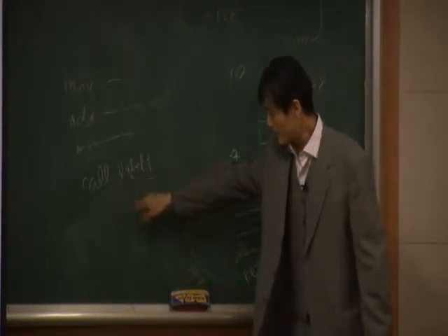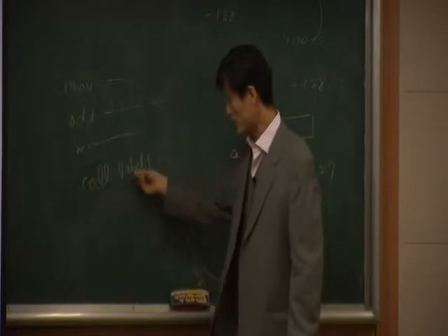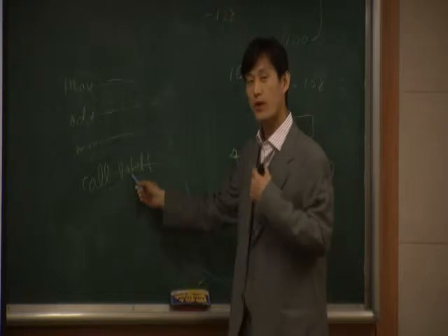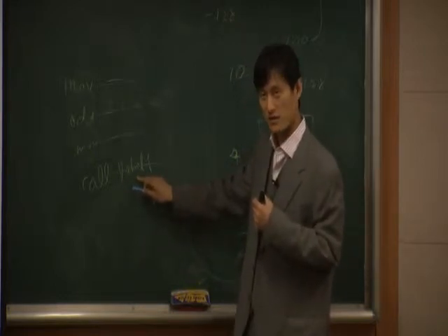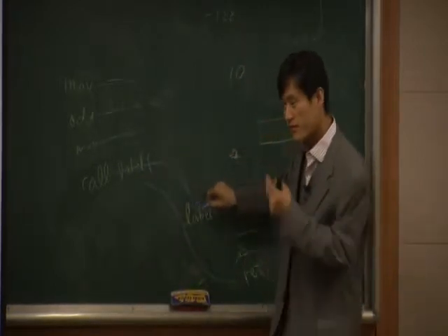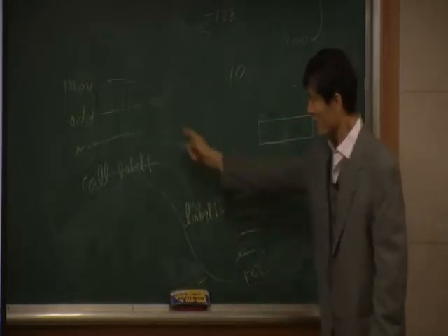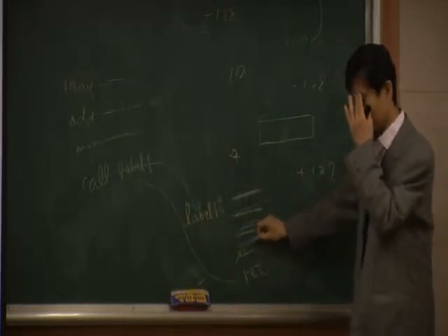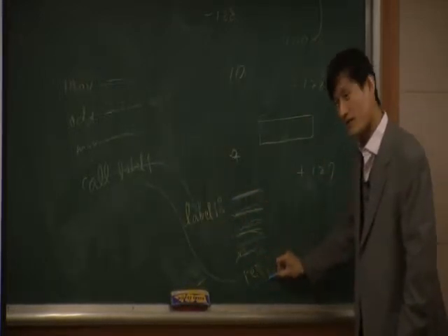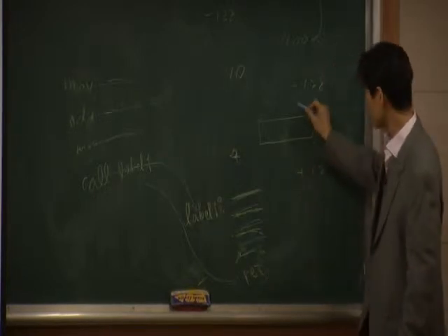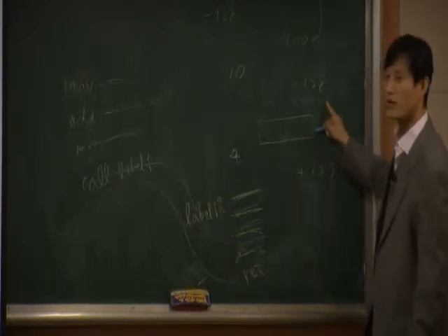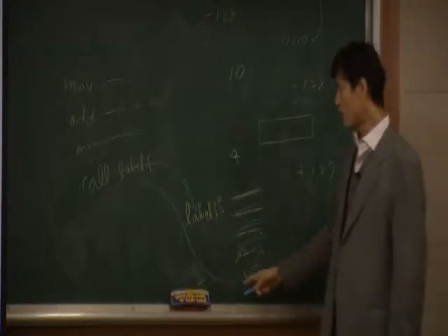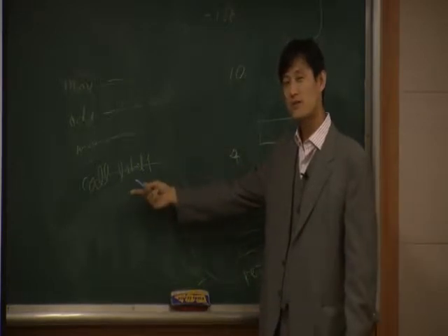Okay, here's the thing. Let's say you execute this instruction. This is a call instruction, and it says label 1. So I know where to jump because it says label 1. So let's jump to label 1. Now you just forget this one, right? I jumped already. I execute each of these instructions, and later I see return. The return instruction is simply RET, no operand, nothing here. Then how do I know I have to go back here? How do I know?